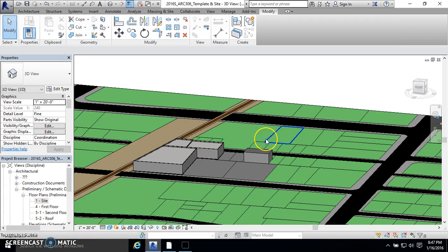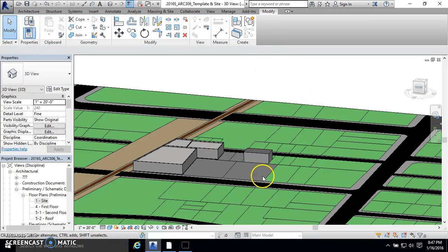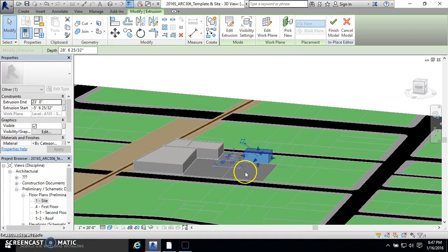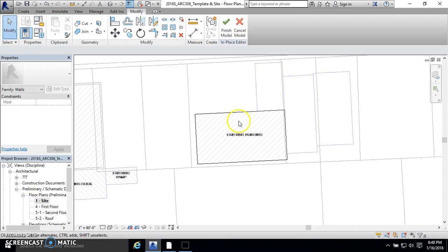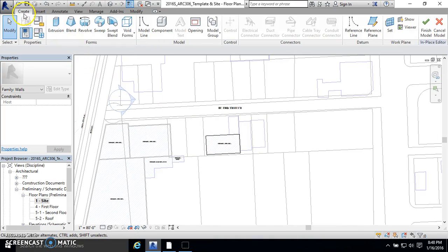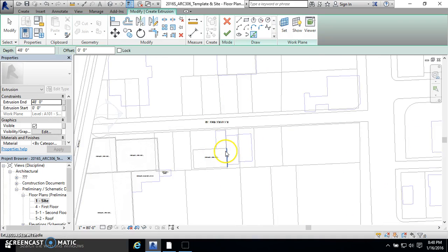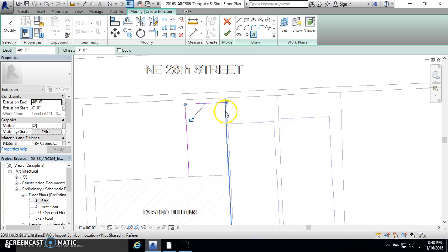So now you can start to see the height. And now you can see that I clicked out of everything, and if I want to go back in, I can edit this, click on that one, and hit edit again. What I'm actually going to do is stay in this, so I can do every single building in this one extrusion.